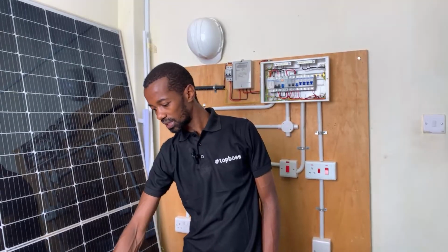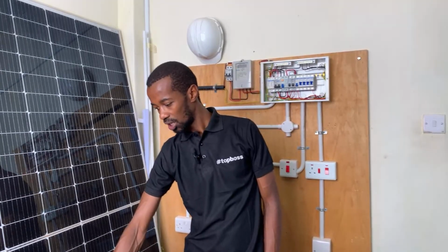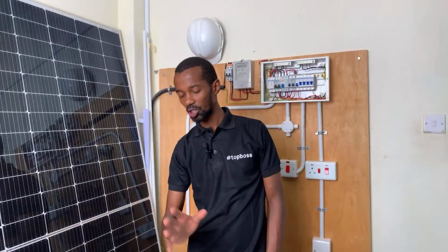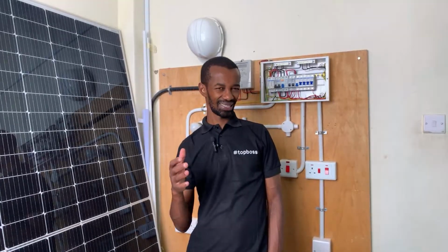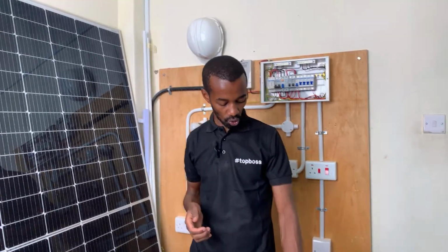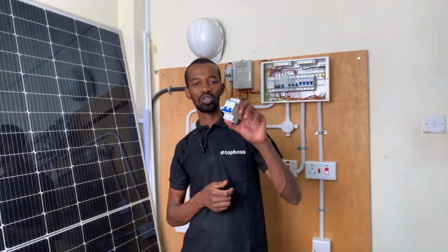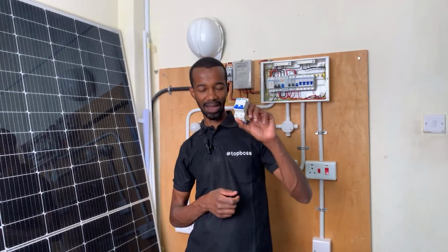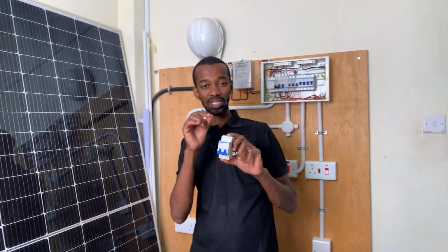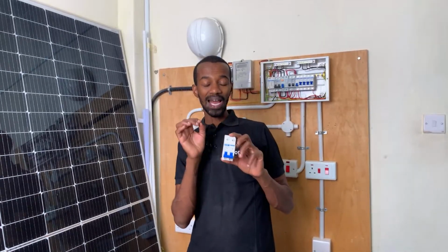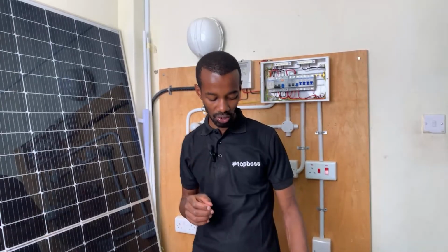Remember, these protective devices are connected so that they can protect the circuit, they can protect the home, or they can protect the building, assuming it is a business. So if there is a motor that has been connected which draws more than 63 amperes, it means that even the cables that have been connected in that circuit are not able to supply that current to that motor.